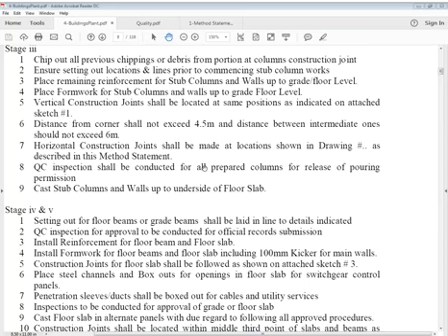So when you want to connect this construction joint with new concrete, we have to prepare this joint first. We cannot simply concrete. We have to scabble the surfaces where new concrete and old concrete butt with each other, the half vertical, then horizontal, then half vertical thickness. These are scabbled. Scabbled means hacked. Hacked means you have to remove the cement paste from there and expose the aggregates fully. Of course, the steel is there. It doesn't matter. Steel you have to clean.